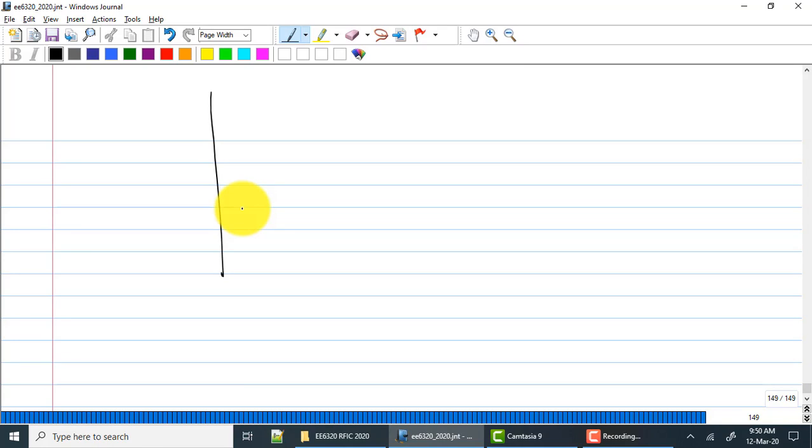First I did the sweep to find the minus 46, like this linear is minus 46. Then cross check whether I'm getting IIP correct. So what you're telling me is you did 2 points. You got some IIP3, you're taking a third point, you're not getting the same IIP3. Is that what you're saying? Okay. So first of all, for IIP3, you need to run a fairly larger number of points.